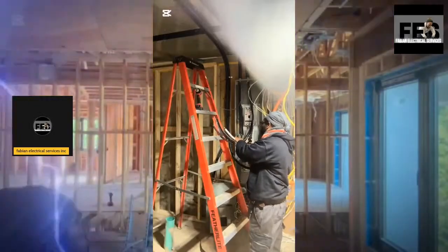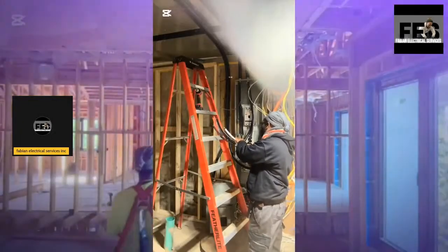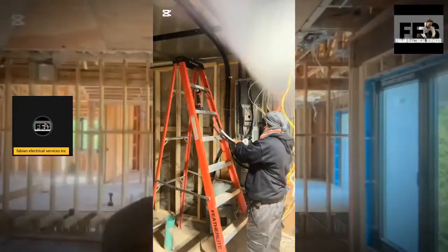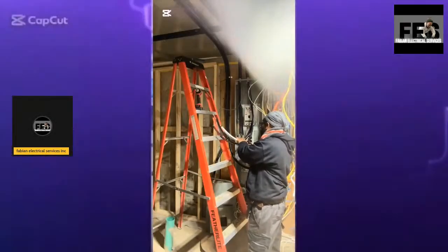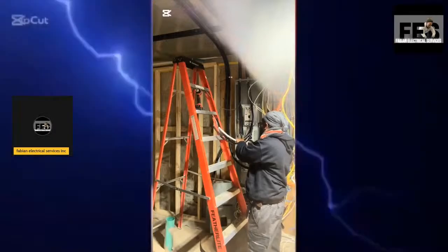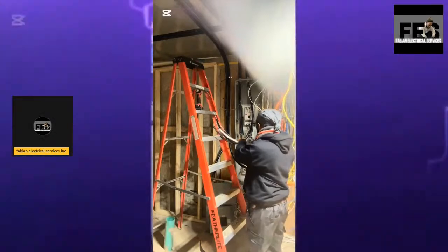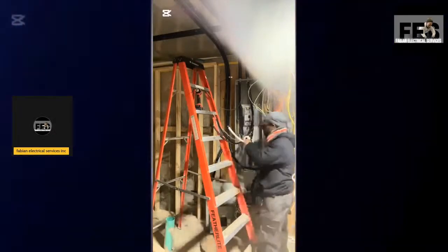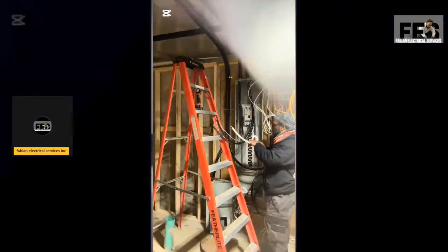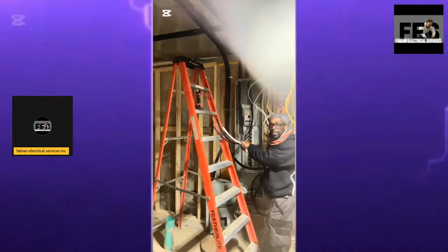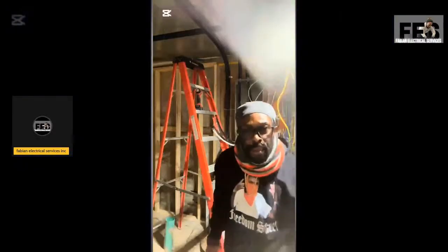We normally phase with the white tape, neutral. That's the color tape that you're going to need. It is a white, it's called an unidentified conductor. So that's what we're going to use, the white tape. Again, for the grounding, when it comes to the grounding and bonding, it's normally a green conductor. So we simply tape it green.